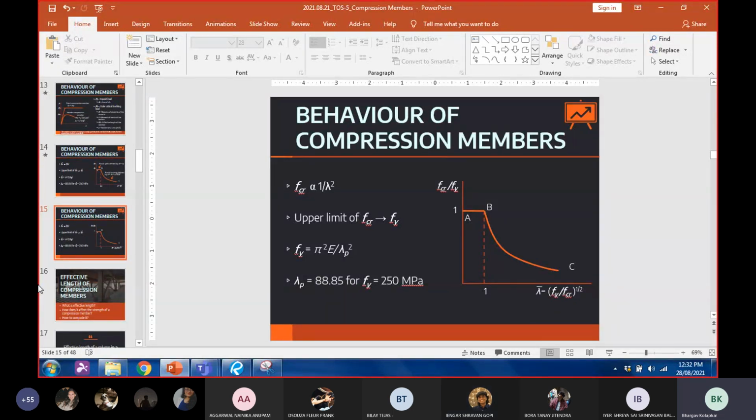For that, we'll have to look at how the bending moment and the axial force vary along the length of that column. You have to look at the bending moment diagram of that column. If you notice that the critical bending moment occurs somewhere in the middle, where the section is a normal section and not flaring out, you'll have to check it at the normal section. And if you find that the largest value of the bending moment occurs at the bottom where it's flaring, perhaps you look at that section for the slenderness ratio.